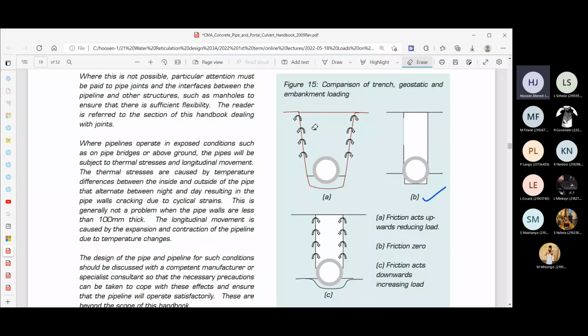But adjacent to the pipe over here, this soil over here, it's loose. You put it back in the trench loose, and it can actually move downwards. It'll settle, so you'll get some settlement occurring above this pipe over here. Right? So what will happen is, for example, the ground might eventually, after a while, look something like this over here. Like that. So above the pipe, you get less settlement because of the rigidity of the pipe. But on the sides of the pipe, the soil can settle more on the sides there. So you'll get this movement. So the soil moves downwards like that on the sides, along the side walls of the trench.